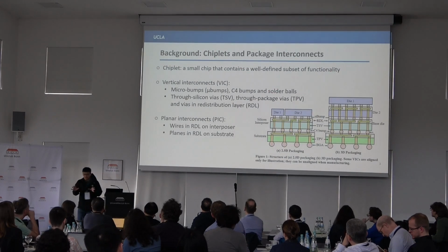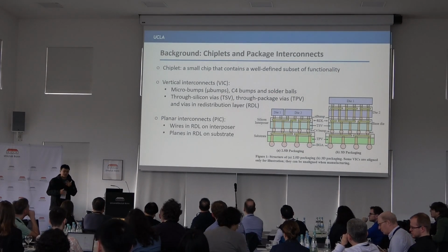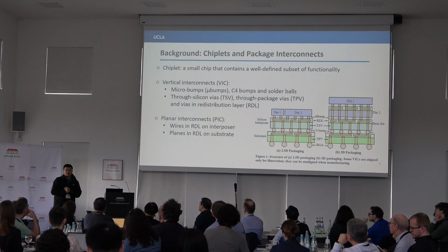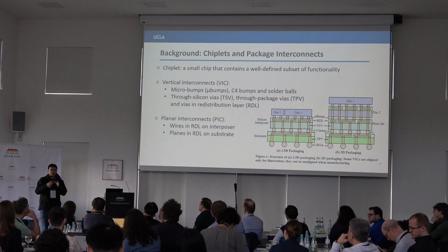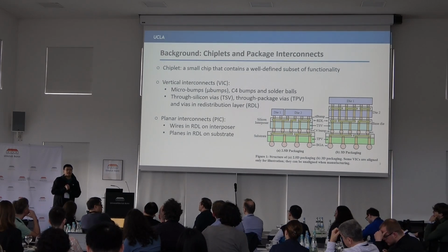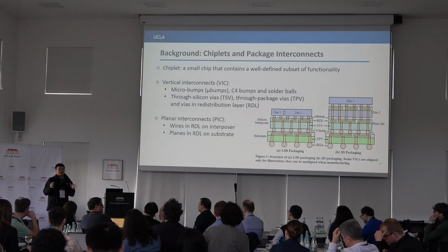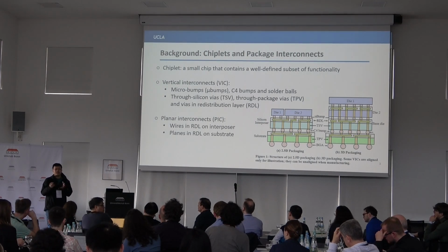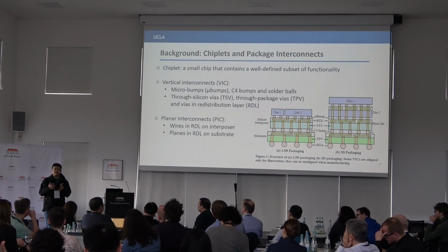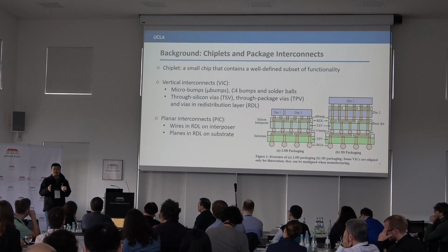We do not adopt the most advanced technology such as backside PDN. But I think this approach can be extended to backside PDN as long as we know, for example, the wire width, the spacing, the via pitch, and the via diameter. If you know these structural parameters, I think it is easy to extend to backside PDN.